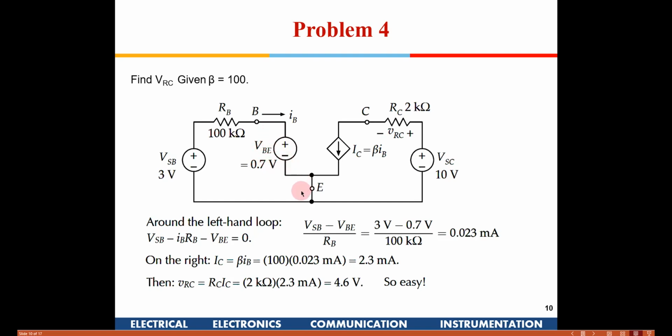Okay, so that is what we need to remember about BJTs. It is not a function of IB; it acts like a forward biased diode. So the moment you apply a voltage, this voltage will remain 0.7. The current can be anything, ranging from a few microamperes to milliamperes, but this voltage would remain constant. So that is how a BJT functions. So this is 0.7 volt.